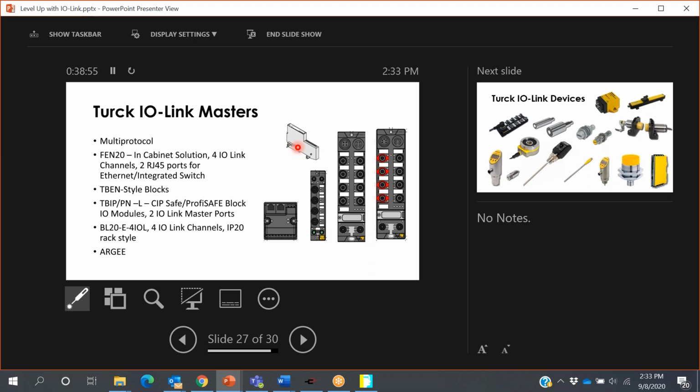They needed 2 push buttons so they could set their slow down and their stop set points. And then they needed to control 4 starters. So that's 2 IO-Link devices, 2 discrete inputs, and 4 discrete outputs. Well, these channels, not only do they have an IO-Link on pin 4, which is typically the black wire, they also have a discrete IO point on pin 2, which is the white wire. So we put splitters in there, connected the IO-Link devices to one half of the splitter, which there was only 2 again, and then the other half we were using as push buttons.